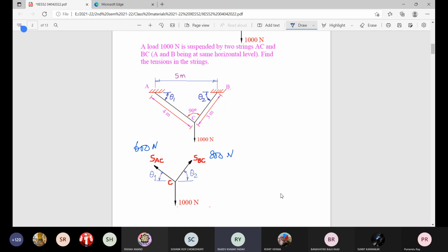Sir, here the magnitudes of the forces are actually proportional to the sides of the triangle that will form. Good observation. Where do we get that from? It's simple geometry. As if it is the joint of a truss, draw the free body diagram and complete that vector polygon.